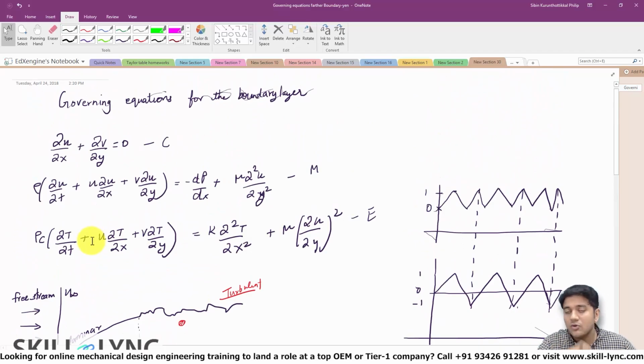So if I take my original governing equations and I am able to solve them so that I integrate only over small time steps and I have a huge number of computational cells, then I don't need a turbulence model. Okay, but this approach is quite impractical for engineering simulations that people attempt these days, right? And that is why we are using a turbulence model, so that we can still capture the effect of turbulence by using a coarser grid and a larger time step.